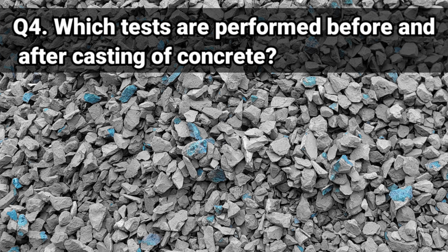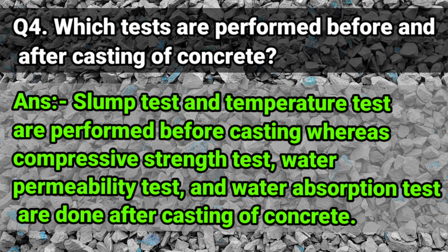Which tests are performed before and after casting of concrete? Slump test and temperature test are performed before casting, whereas compressive strength test, water permeability test, and water absorption test are done after casting of concrete.